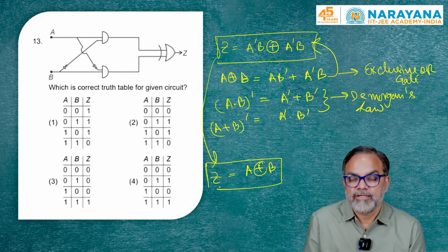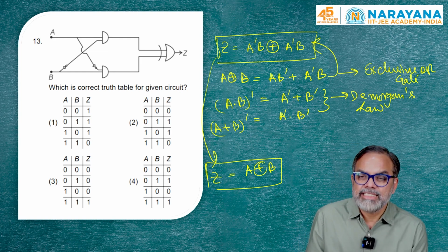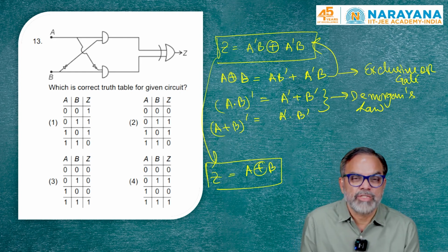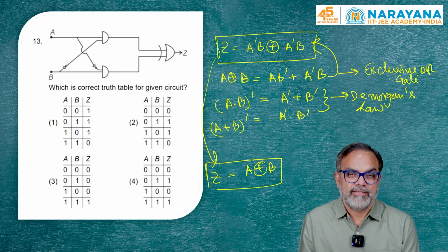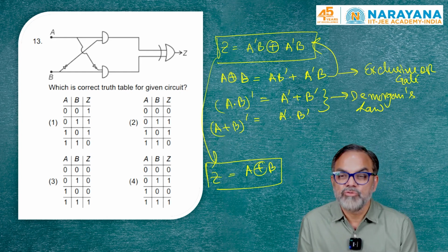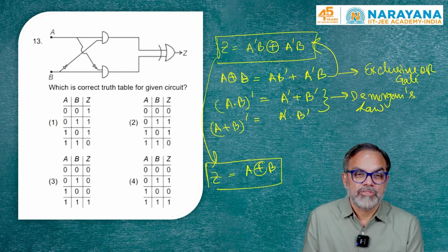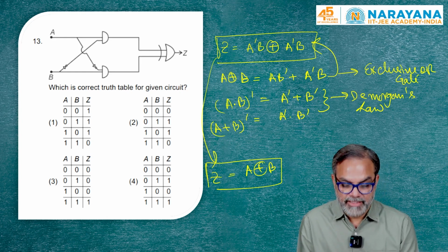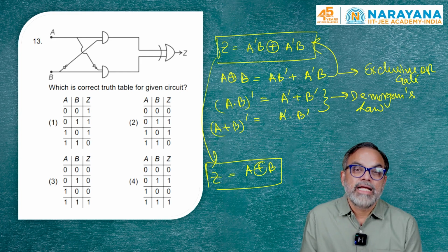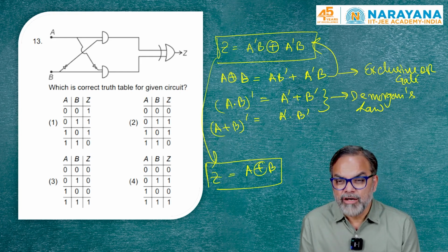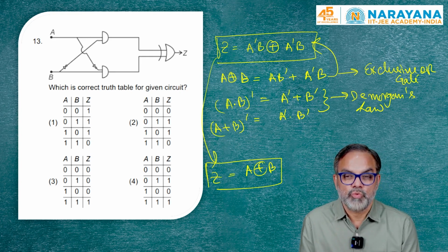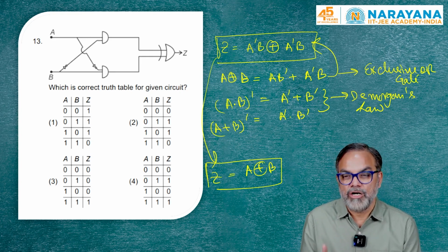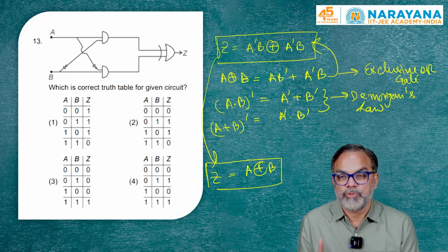Now the exclusive OR gate is a very less visited topic by students, so they may find it difficult. So I'll put it in the category of difficult, not covered usually, not part of NCERT. Most of the students may find it difficult to handle. In exclusive OR gate, I get output as true when we have an odd number of true inputs.